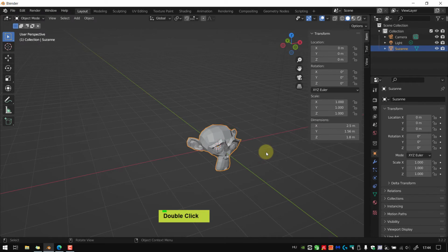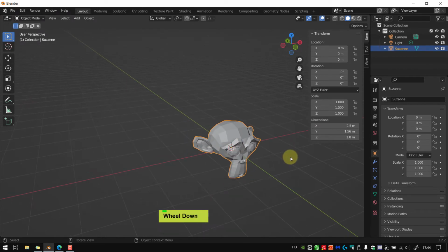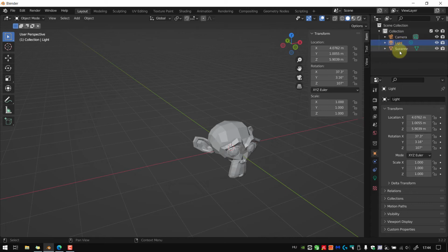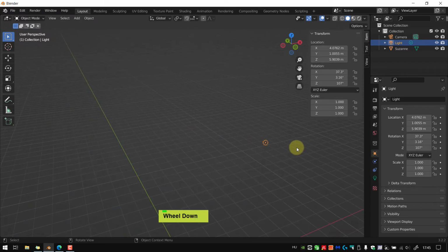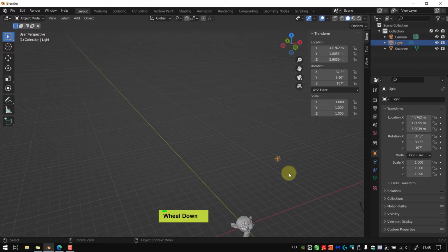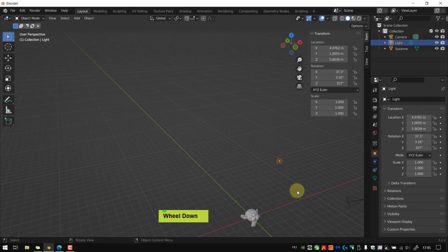So here's this item, and if you want to zoom in automatically to make sure that it fits to the scene, or you lose something, for example, you don't know where your light is, you select your light in the outliner, and you want to focus, zoom, and make that in center, you have a hotkey that is the comma hotkey in the numpad. The numpad is the numbers on the side of the keyboard, if you have that particular part of your keyboard. And this is the numpad dot that actually is a command of fit.